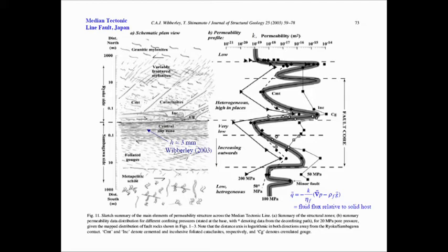Permeability, by the way, is the quantity which gives you the mass of fluid crossing unit area in a porous medium in terms of the viscosity of the fluid and the gradient in pore pressure within it, corrected by gravity. That's called Darcy's law, if you have not encountered that.